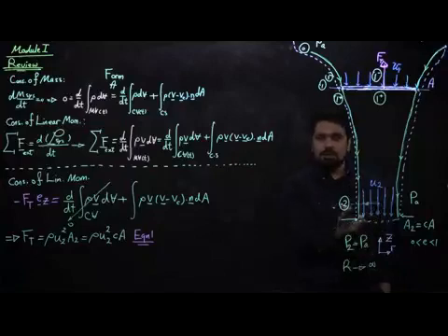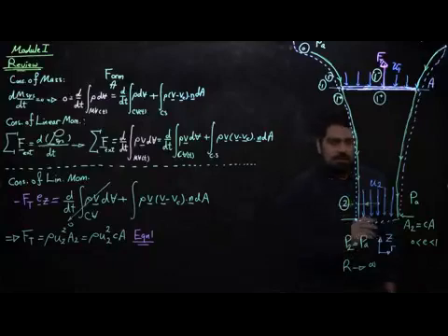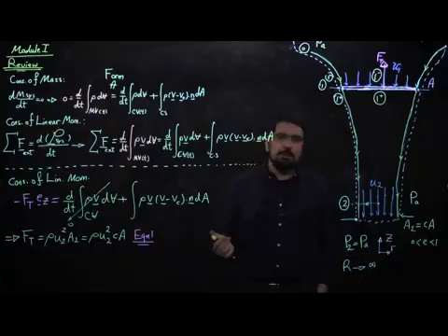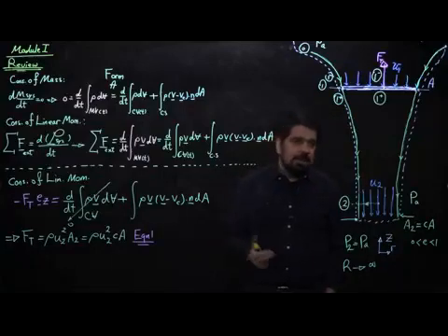So if outside this jet pressure is atmospheric, inside this jet at any point pressure will be atmospheric too. So this idea that pressure everywhere here is atmospheric is the use of Euler equation normal to streamlines. Again, you can see the subtle use of certain concepts that we have learned in module 1 that helps you to really simplify this problem.